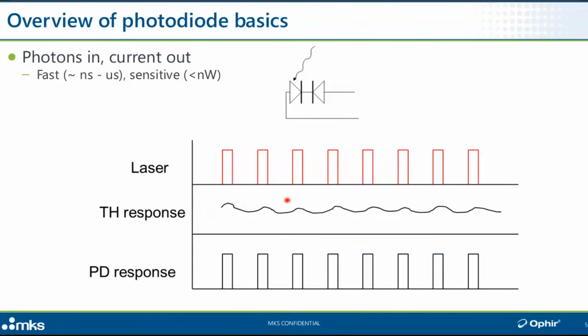So if we are using such a detector to measure a laser that's pulsing at a couple of hertz, the sensor has absolutely no clue that the power that's coming in consists of repetitive pulses. It thinks power is power. At best, or worst, depending on how you look at it, if it's pulsing slowly enough compared to the time constant of the particular sensor, there might be a little bit of a ripple in its output signal, but not more than that. So you can't use thermal sensors, not standard ones at least, to measure the energy per pulse of a repetitively pulsed beam. We use other detectors for that, pyroelectric or semiconductor again.